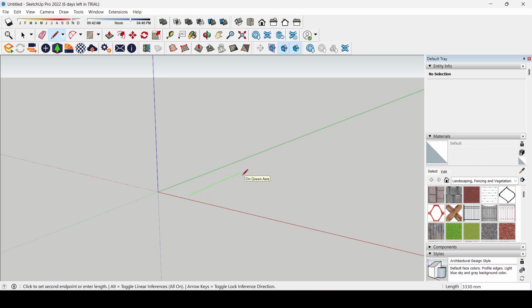You can see down in the bottom right-hand corner that we have a measurement in millimeters, and you can see if I drag this and I click, I have a line here, and I can stop drawing lines if I press escape like this. If I want a specific length for the line, I can just click and write 300 and press enter, and it will make a line that is 300 millimeters.